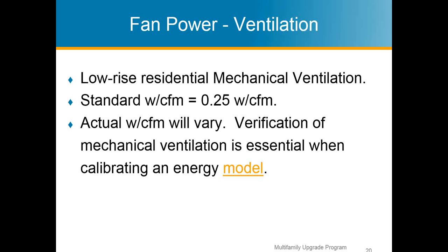So I'm thinking of these older properties that we see out there, built in the 70s or later. The fans could be just old, outdated. They're running a lot. They're super energy inefficient, meaning that they pull a lot more watts but deliver less CFM.